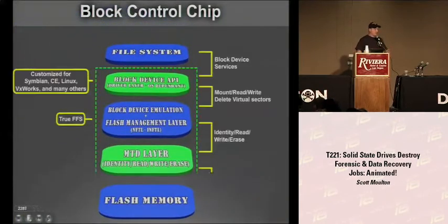But ultimately, the point becomes, when you plug it into your computer, it has no processor on the device. It has no way of calculating anything, so it has to use a driver on your system. When you plug in a memory stick, the mass storage driver starts up, and at that point it takes over and has to do all the fundamental work for what's happening on the memory stick, using your host processor to do that. Because it has no processor of its own, all the work for ECC, changes, bad blocks or wear leveling has to physically be done inside your computer using your processor, passing it back and taking care of the chips itself, because the stick has no way of doing that.